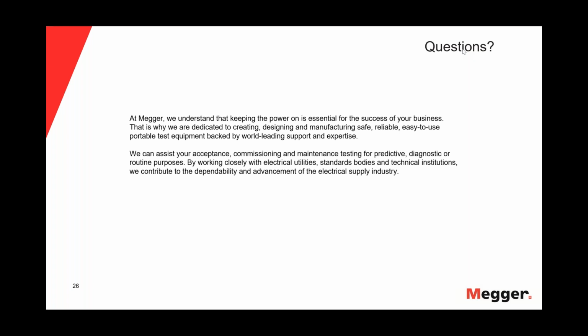Thank you, Henning. Javier, can any cable test be done on an energized cable? Well, in the case of the VLF test and the tan delta test, there is no way. I mean, we need to de-energize the cable to connect our power source, or VLF.